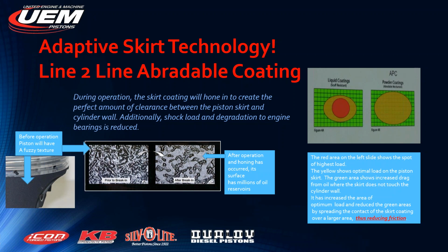Now that provides an additional lubricious component, obviously, that stays there and stays in place, protecting and reducing the friction and everything else. But because it adapts that piston to the cylinder, it keeps the piston square to the bore, which means the rings are square to the bore, and that the rings can do their job much more effectively in keeping the combustion pressures up, reducing blow-by.